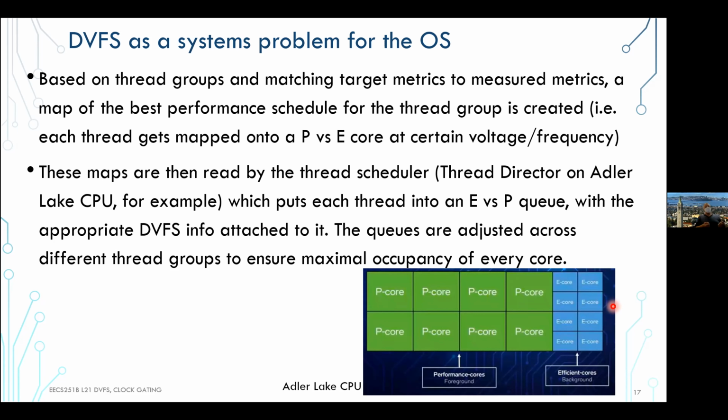So the scheduler needs to really understand the state of each core, what the occupancy is. It also wants to group. The new thing here is these thread groups, right? You look at each thread and look at the types of computations and resources that it needs in these operations. And you're trying to group the threads by similarity so that you can schedule voltage, frequency, and which core it goes on per group rather than per single thread. That makes things a little bit easier because you're bundling. If you have 100 threads, maybe it's 10 groups. So the problem dimensionality becomes smaller.